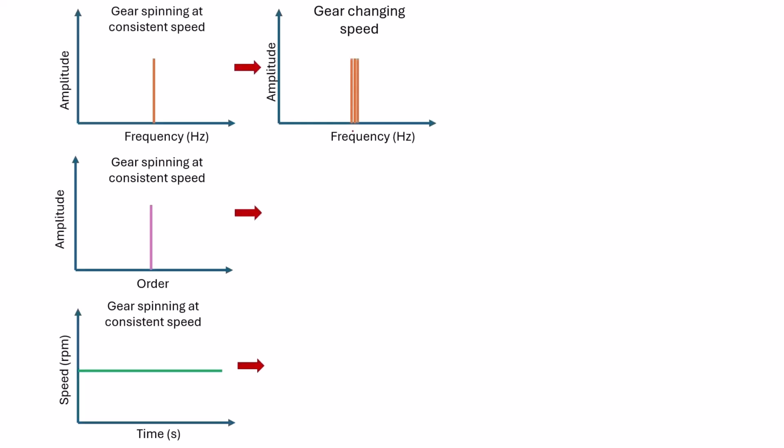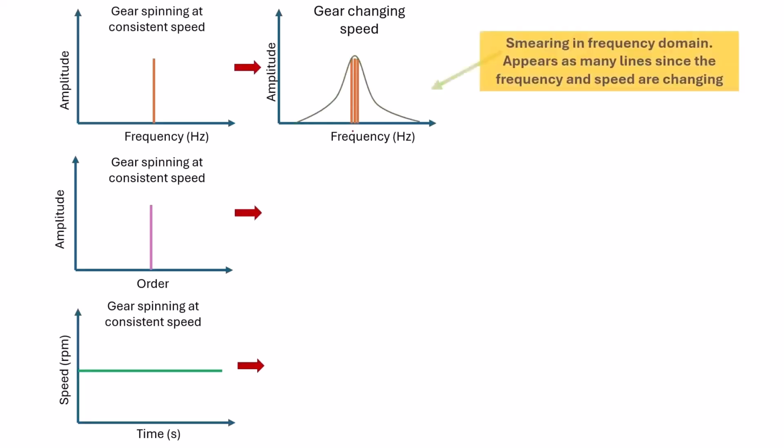We'll end up with multiple peaks, so it ends up with a smearing effect in the frequency domain. And this can be a problem for the Cepstrum algorithm, because if you're trying to measure where those periodic components are and everything's smeared, you're just really not going to get good results.